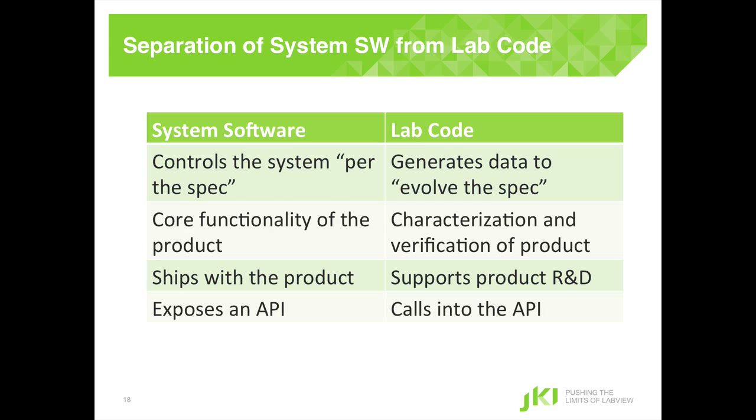don't have a great setup slide for this, but one of the things that we've done is we've exposed all of the different subsystems that are dynamically loaded through a private API, and then we've created language bindings in Python, and then the LabVIEW code basically can call Python-based recipes that call into the LabVIEW subsystems. We're using Python as a text-based recipe language that allows the product development team, like the chemists and the process engineers, to actively participate in some of the highly sequential, non-real-time logic of the instrument.